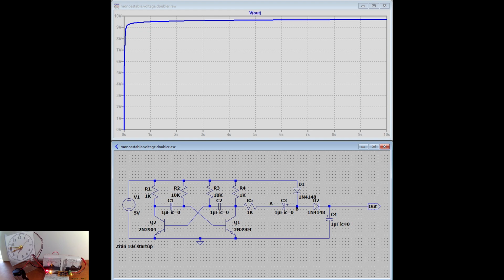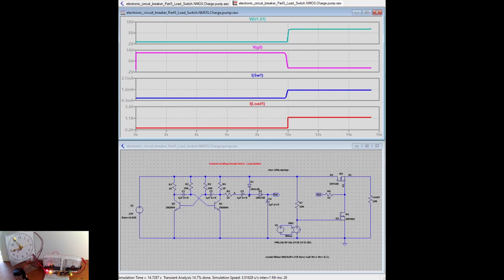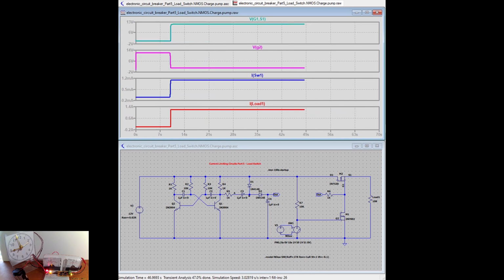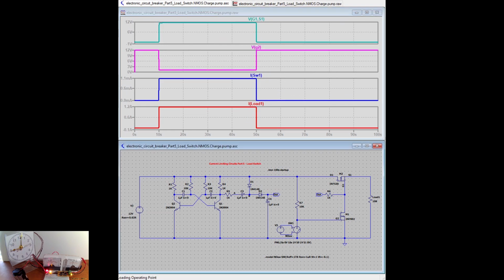2. A charge pump circuit, a kind of DC to DC converter, to increase the main power supply voltage above the gate threshold voltage. A charge pump can be as simple as a monostable voltage doubler. Here is the circuit with the charge pump in place of the additional power supply. However, the use of a charge pump requires a switching circuit, adding extra circuitry and the need for protection against noise generated by the charge pump.